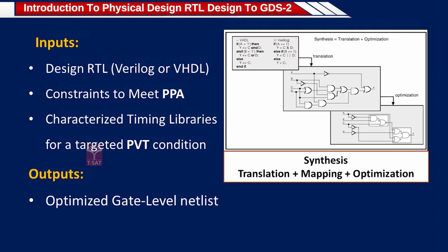One is logic optimization and one is cell changes, meaning logic restructuring, and we can change the cell type. Logic optimization means the same logic, whatever logic you are seeing in the diagram, A to Y, B to Y, functionally should be the same but can be realized using fewer gates.